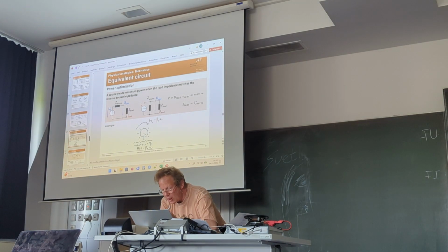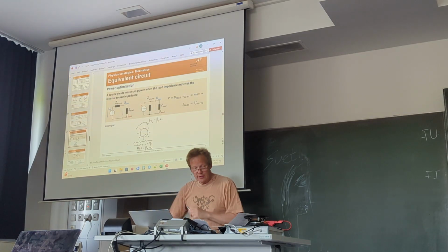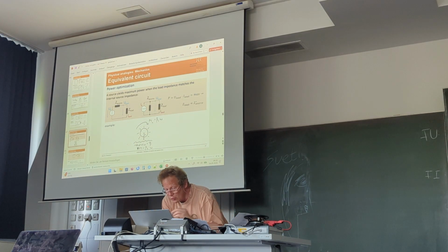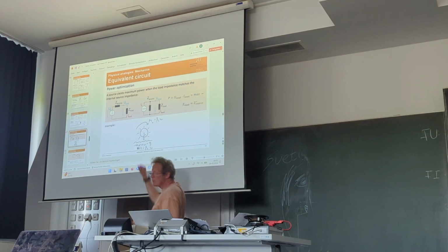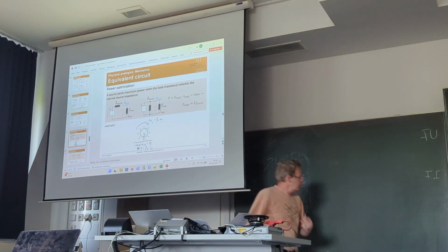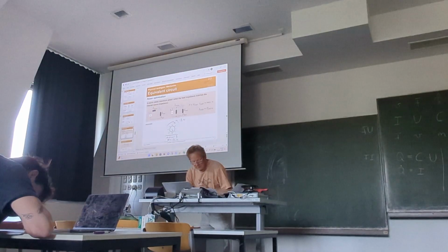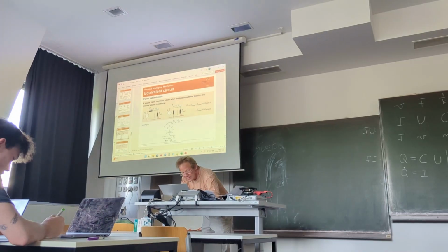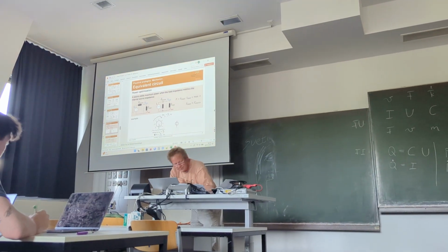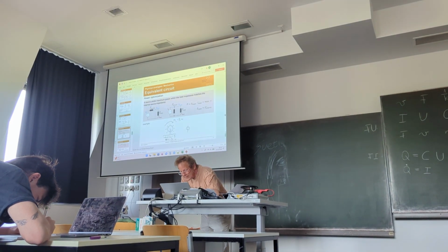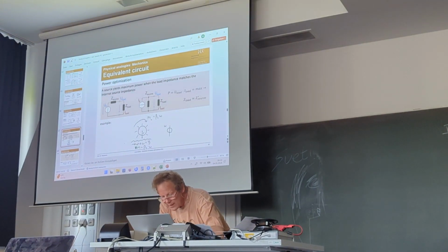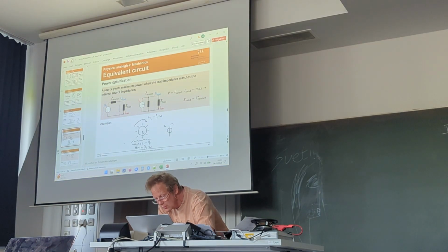Okay, and now we can draw an electric equivalent circuit. We can say we have a source. The source is velocity or angular velocity, according to our analogy, the voltage source. So instead of voltage, I write here this omega. Then we have a resistor corresponding to this beta 0.